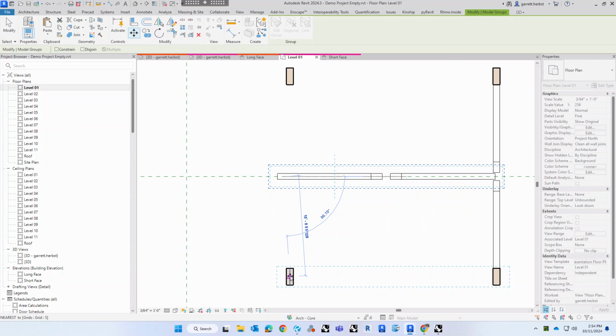And a lot of times too, if you're not working with a tower shape like this, and you have a much larger building, a lot of times your bracing is going to be interrupting program and basically diving down into it. So again, coordination with your engineers is very important. But thinking through this in the early stages helps to alleviate some of those problems that you run into.